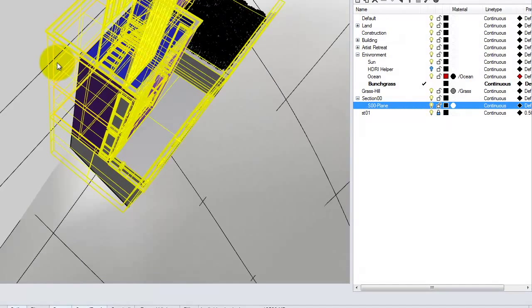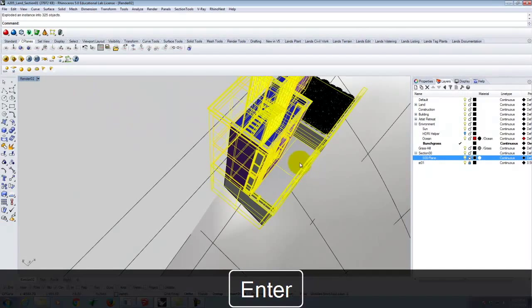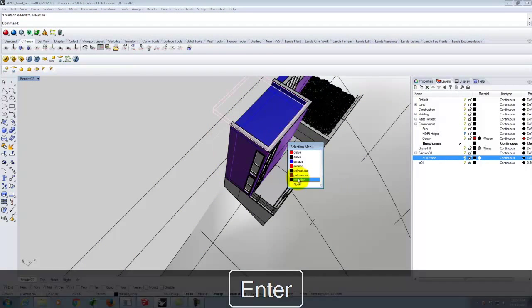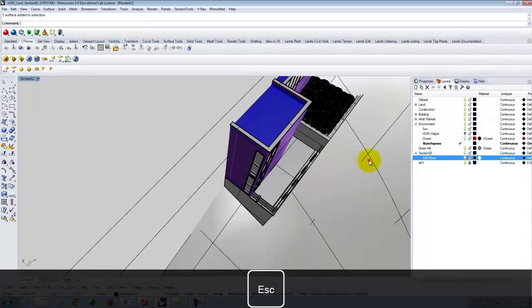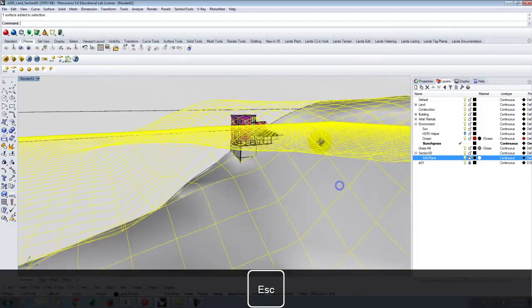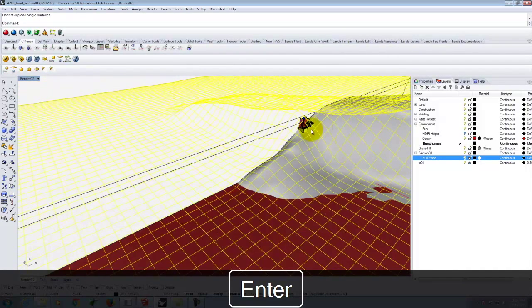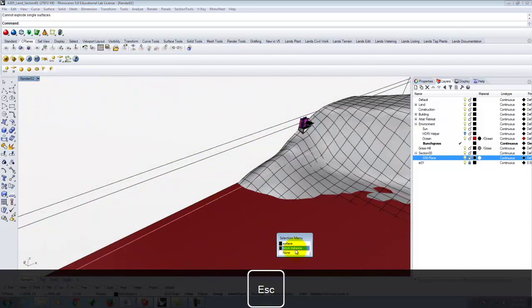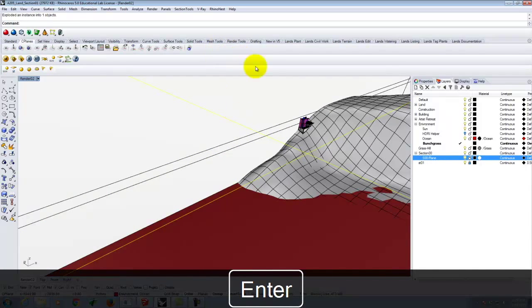If I'm going to do what I'm going to do now, I do in fact have to bring the block fully into the scene and start to work with it. So I'm going to take the block and I'm going to type explode, which then drops the entire block into the scene such that I can pick any one of the individual surfaces again. Okay? Likewise, for the ground here, I'm going to go ahead and explode that and bring that in. Now I wasn't able to explode it. The water is a block instance, so I'll explode that like that.